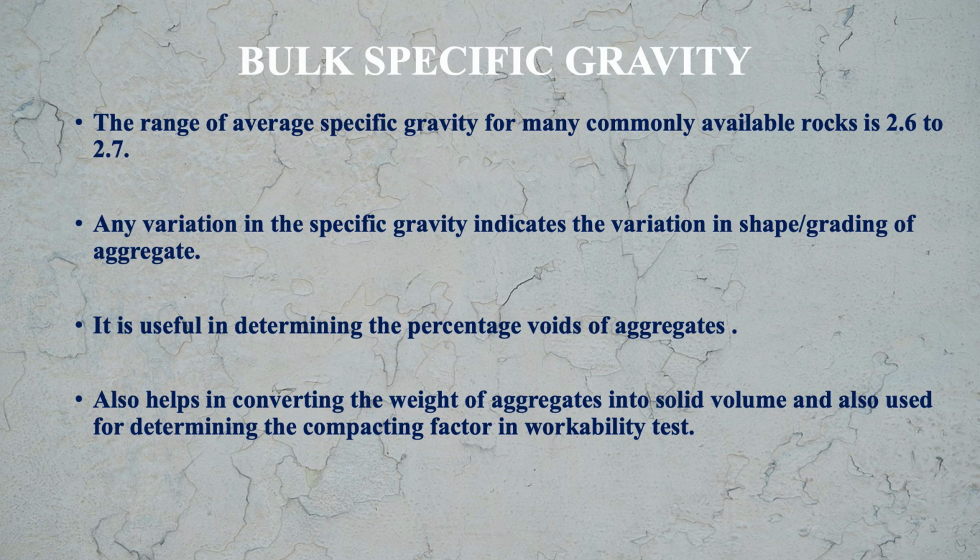Now it is useful in determining the percentage voids of the aggregates, and also it helps in converting the weight of aggregates into solid volume, and also used for determining the compacting factor in workability tests. So these are the uses of knowing the specific gravity of the aggregates.